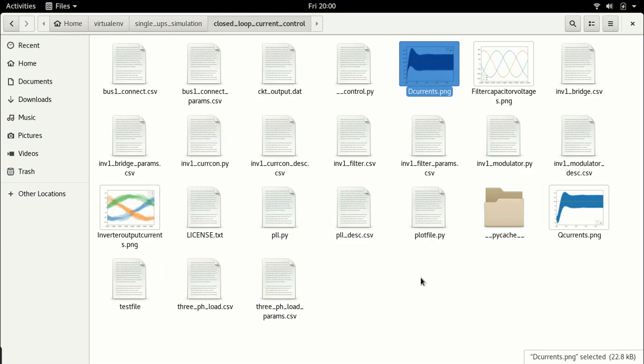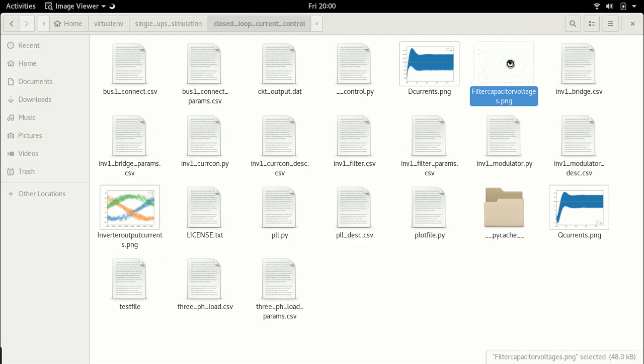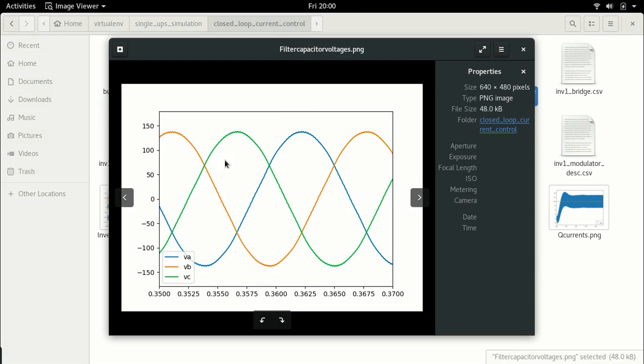So now the question is, this resulted in an output voltage of this nature, and I already said that this output voltage is not a regulated voltage. For example, if I were to consider a 208 volt 60 hertz typical voltage, this 208 volts is a three-phase RMS voltage, and that means it is 120 volts single phase RMS. And that 120 volts again translates to 170 volts peak. So if you see here, I'm not even close to 150. And what this means is that my voltage is not regulated.